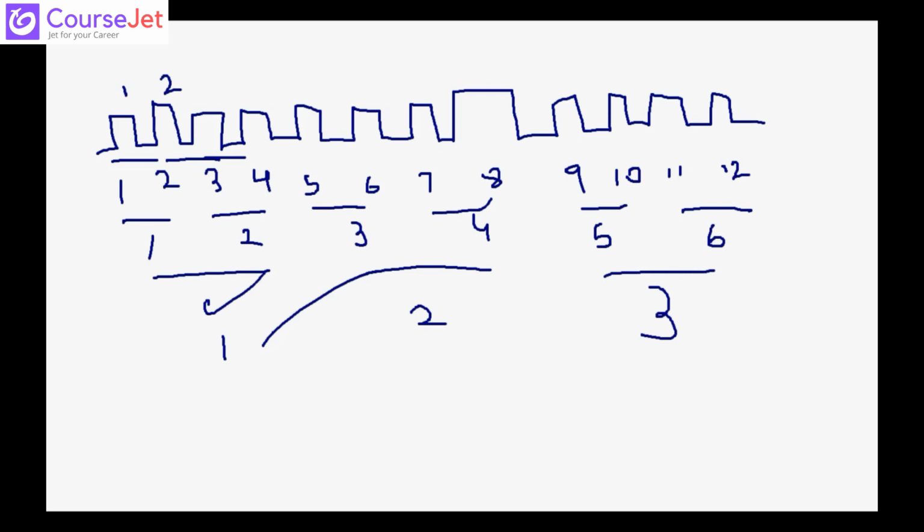11.0592 you are dividing it by 12, you are getting 921.6. This whole 12 pulses you are considering as 1. You get 921.6 kilohertz. 921.6 you are dividing it by 32, you are getting 28,800. Now this 28,800 I have. If I divide it by 3, that means if I read 3 as 1, then I get 9,600. If I read 12 as 1, I get 2,400.